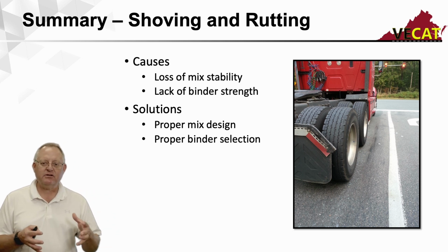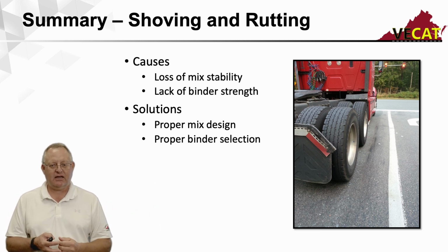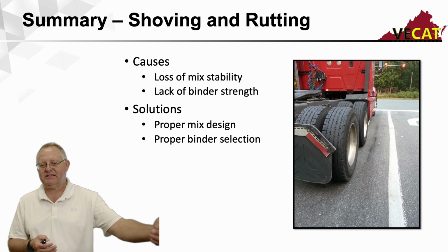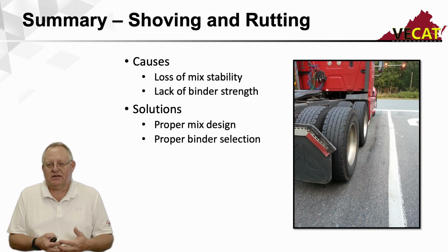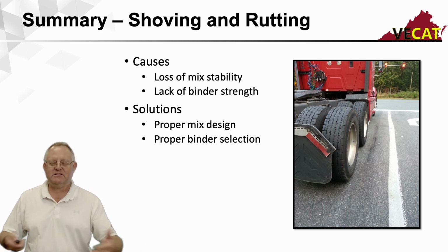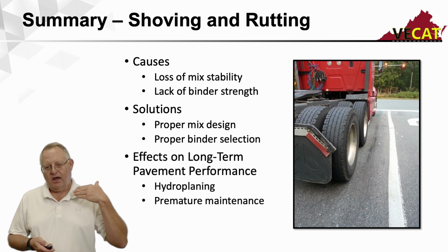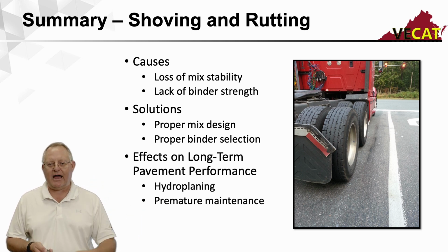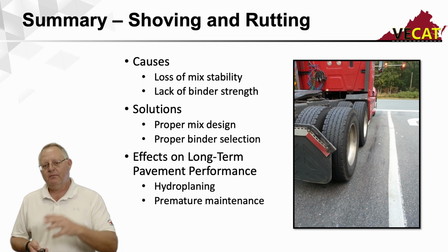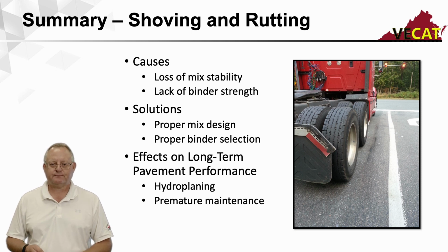Now, you as the inspector, that is not a decision you make. That goes back to the person that puts together the contract itself. But that is an outcome, a mixture-related issue that wasn't a mix issue. If the wrong binder was selected, the wrong mix was selected, it goes back to the contract itself. But it's things you got to be aware of because this reduces the life of the pavement. And what will happen is if this is out on a long stretch of road and you have rutting, you can get hydroplaning, which is a safety issue, but it also leads to premature maintenance. Things neither one of us want to deal with.